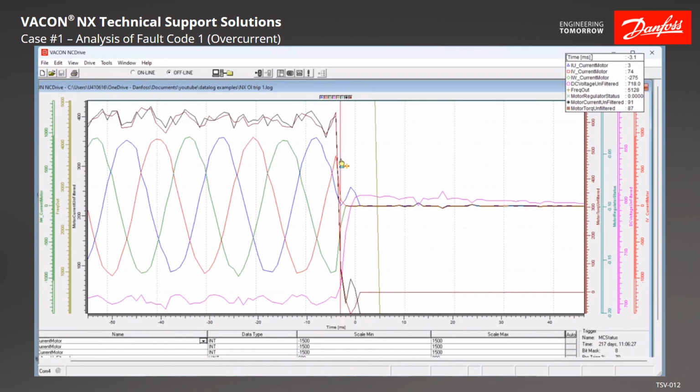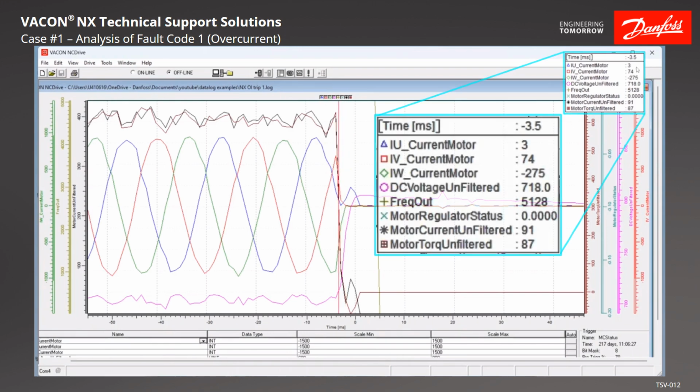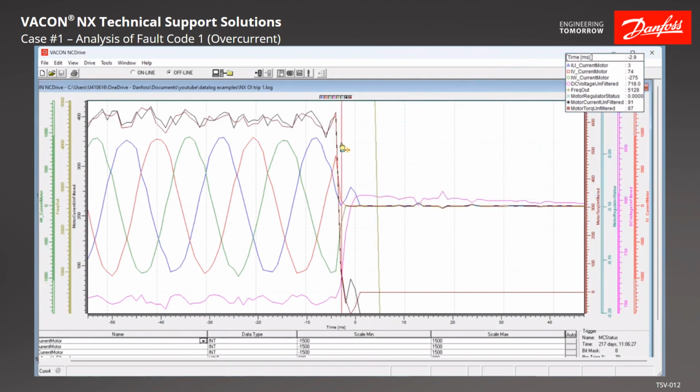So we get to this point and we can somewhat see our currents no longer are adding up. Right at this point, we have a negative 200 left over, which is about 20% current. And you can see this is where DC bus is really starting to rise. Now DC bus, anytime you do shut off a motor, will jump a bit simply because you aren't loading DC bus down anymore.